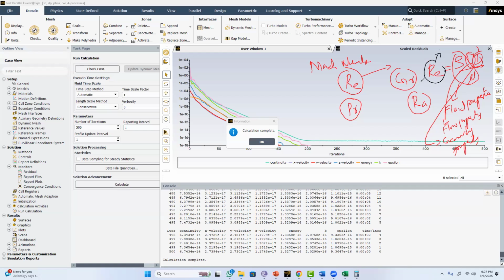Then your drag coefficient for your aircraft and for my aircraft, if the Reynolds number is the same, we should be able to get the same result. I'm not talking about a different aerofoil shape, that's a different story, but the same aerofoil shape where only the conditions are different. The velocity at which it is flying is different, but the drag coefficient should be exactly the same.